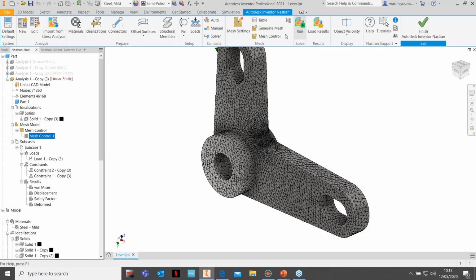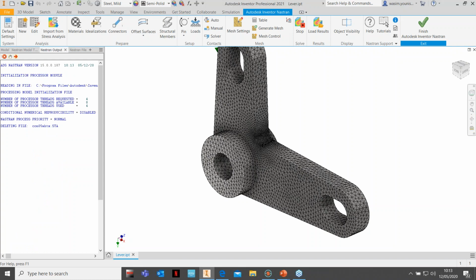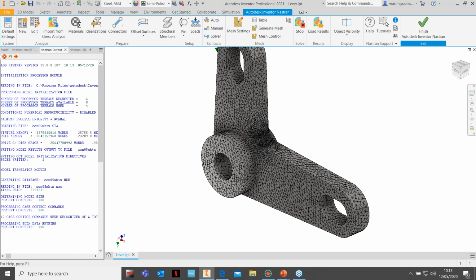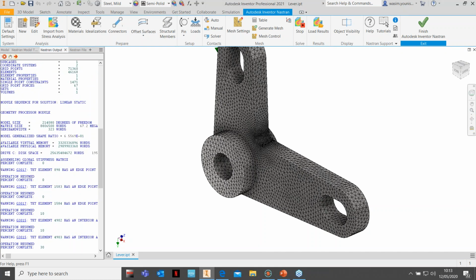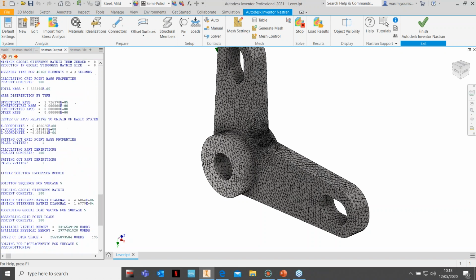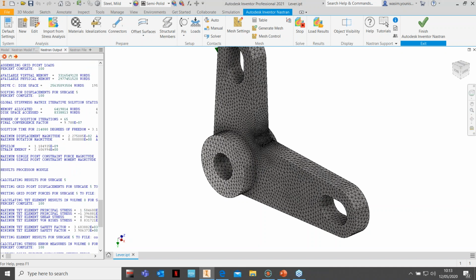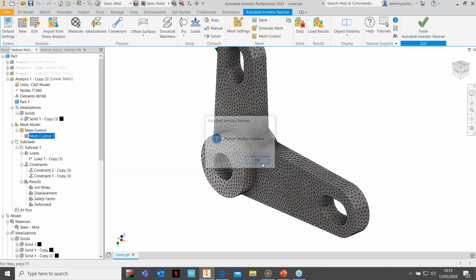And obviously if you have an assembly, then these can take longer to run. And obviously you could start from a fine mesh, and then maybe you put a fine mesh like this. Maybe you don't have to go through 4, but ideally 3 is minimum. But based on experience and intuition, you might end up just doing 2, if not 3 analyses with different meshes.